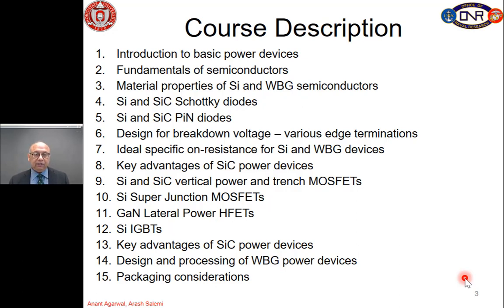We will start with a very fundamental introduction to power devices, which is basically the purpose of this first lecture, and then we will provide you basic background on fundamentals of semiconductor, talk about material properties, and then we will talk about Schottky diodes and pin diodes and edge terminations, key advantages of silicon carbide power devices, and then we will get into power MOSFETs and gallium nitride edge FETs or HEMTs, which are high electron mobility transistors, finally silicon IGBTs, and also talk about key advantages of silicon carbide power devices